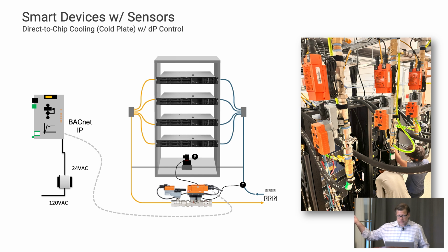This one's actually, a lot of talk about clouds and data centers and data lakes. This right here is an application for a chip manufacturer that came through and needed a specific style of control for these particular server racks. This is direct chip cold plate technology. And what's actually happening, that's our EV4. We're taking a DP sensor, putting it across supply and return, and how they want to control these particular servers is by a DP.